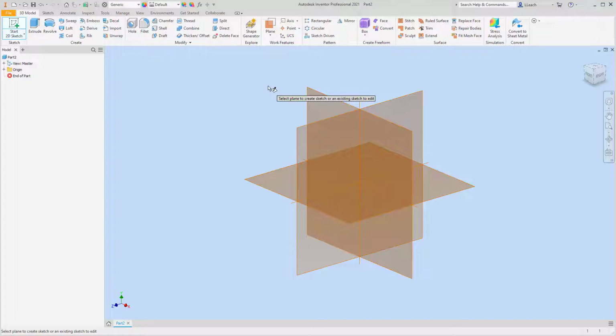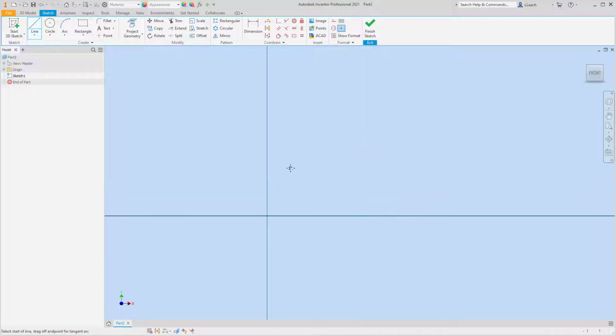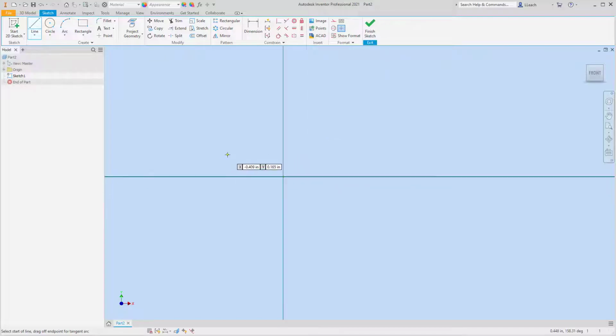start at 2D sketch. I'm going to draw it on this XY plane. So I'm just going to create the front, almost like a front elevation view, and then extrude it back to start with. And I'm also not going to worry about the chamfers, the angled edges or corners or anything like that at the beginning. So I'm going to start with a line, and let's see how I can do this. So the whole width of this is 3.5. So maybe I'll just start with that.